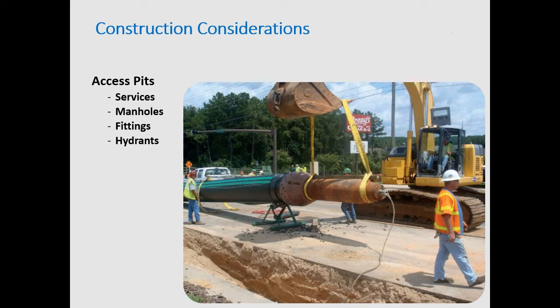The water is a little more difficult. You're really going to be having a pit at every hydrant because you have a T there. You can't burst through those fittings. Any deflections, any ductile deflections, any pipe upsizing or reducers, you're going to need an excavation there to replace it. Otherwise, it's hit or miss on whether or not a contractor is going to be able to burst through those fittings. And you're going to be replacing the hydrants most likely anyway for your fire coverage. So those are going to be access pits.